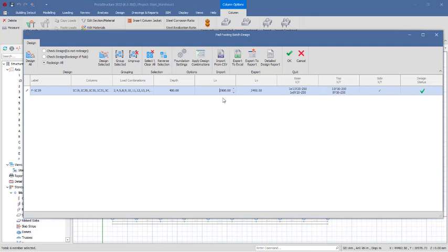You see, now it has passed. This is 2.5 by 2.4. Let me reduce this and check that 2.4 by 2.4 has actually passed. Let's check 2.3 by 2.3. 2.3 by 2.3 failed. So 2.4 by 2.4 right there has passed the design. All right, so we go by the 2.4. This is how you actually change your footing to square footings when it comes to grouping.